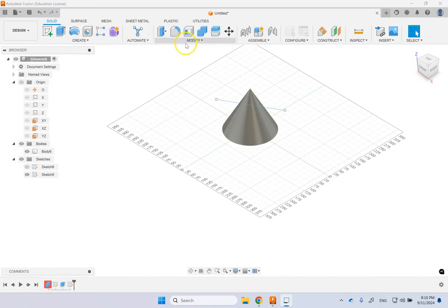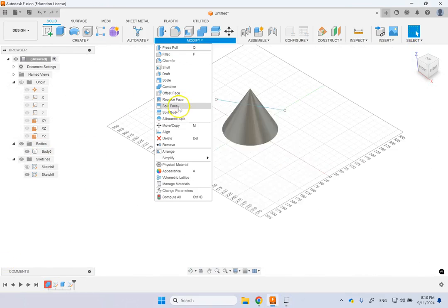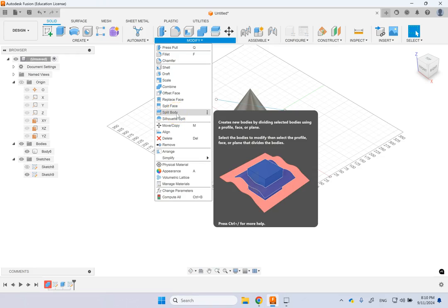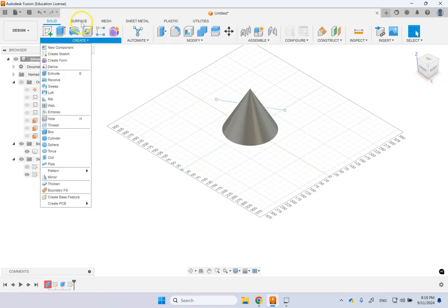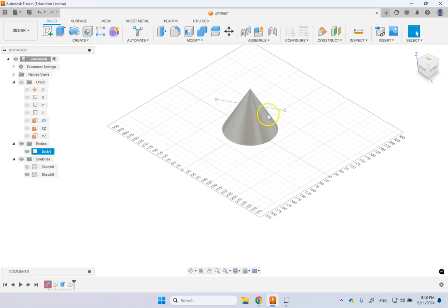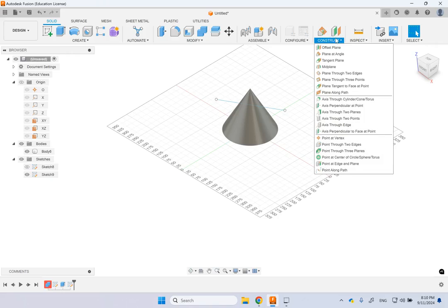The next command I want to show you is a split. So you want to split an object with a plane or a surface. Here we do it with the plane, but later when I teach the surfaces, I also show you how to cut a body with a surface. So here I have this cone and I have this line using which I want to define a plane and then cut that cone with a plane.